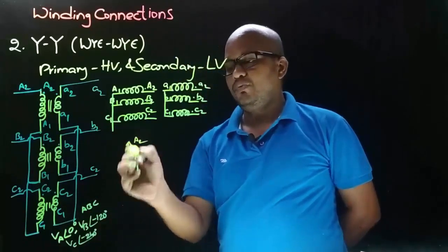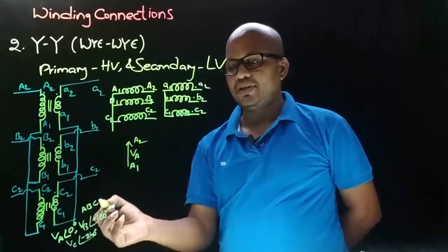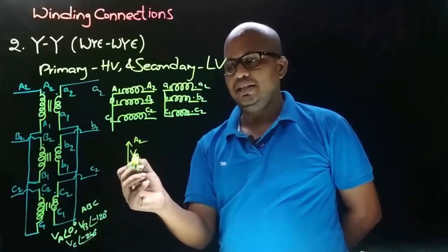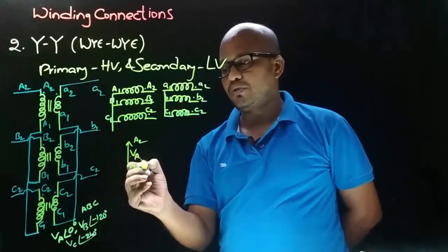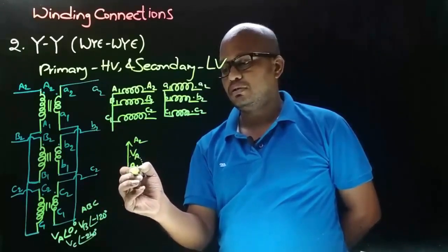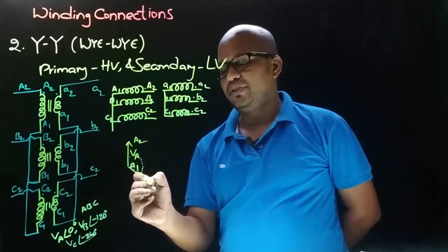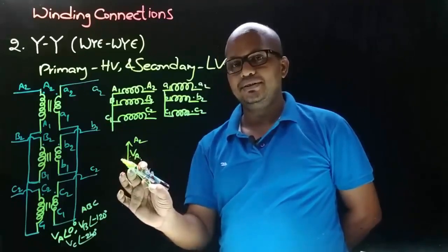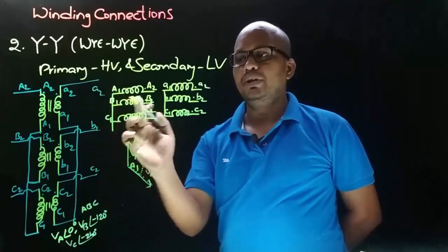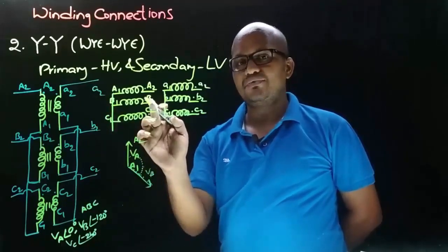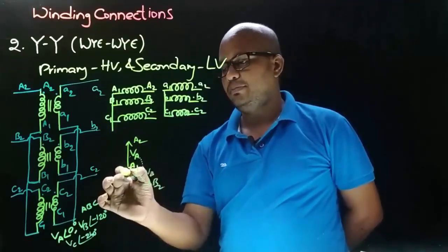Okay, so to VA phasor at an angle minus 120 degrees, there will be VB phasor, and to this VA phasor in clockwise direction, because minus 120 degrees, up to 120 degrees there will be VB phasor, and here we need to decide the terminals. So here in winding connection, VB is having B1 and B2 as terminal, and we are taking the connection from B2, means arrow will point towards B2. So obviously this will be B1.